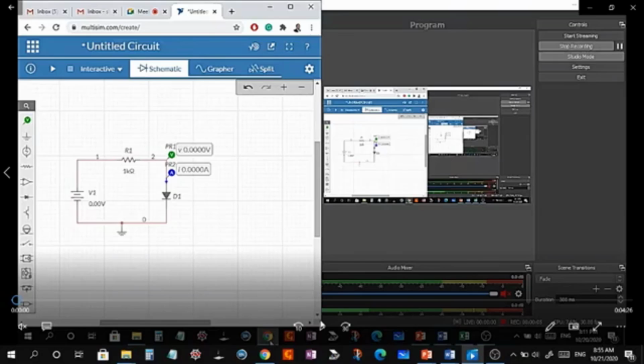connect all the components. Let's say in this circuit we have this DC source or battery, then connected in series with resistor R1, 1 kilo ohm, and then connected it with the diode D1. Okay, so this is the DC source, this is source positive. Based on this polarity of the battery, we can expect the current to flow clockwise. Okay, clockwise, and then you see this positive is connected to the anode of the diode, and then the cathode of the diode is connected to the ground.